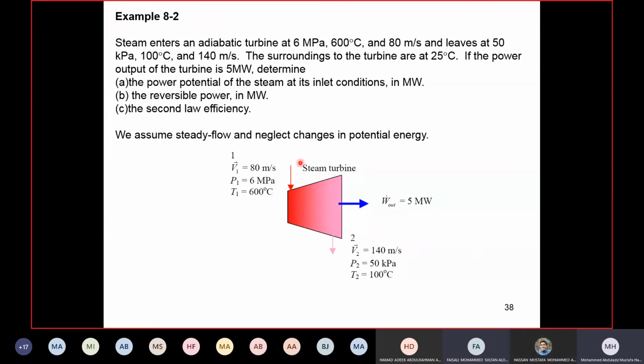Yes. Okay, so from this data, states 1 and 2, inlet and exit, I can calculate the work per kilogram. And why is this being given to us? To calculate what? Mass flow rate. Very good. To calculate the mass flow. So this is what we call the sizing of the turbine. If it does not give us this, it gives us only the work per kilogram.